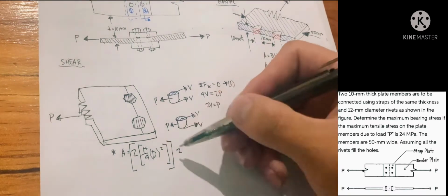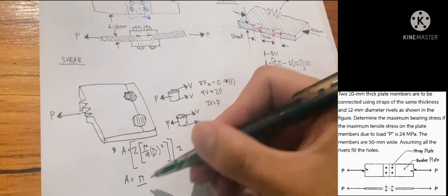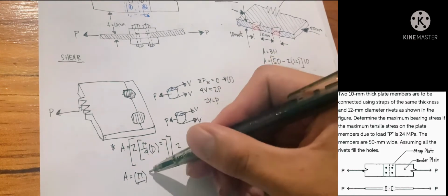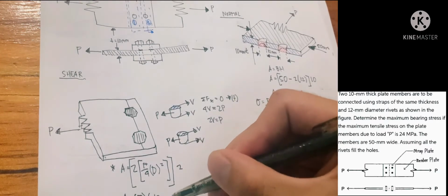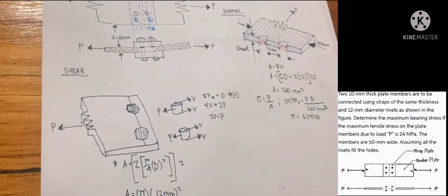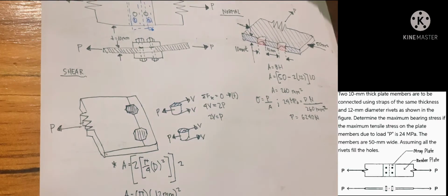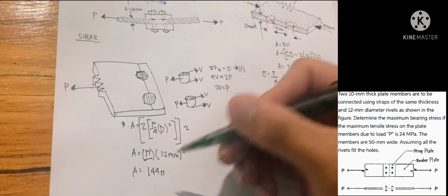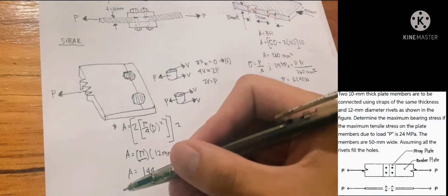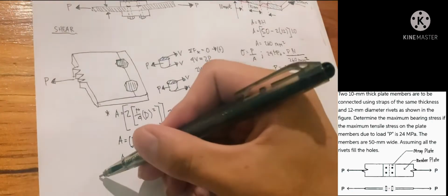So the first 2 is for our shearing formula to be in equilibrium, and the second one is because we want to consider every rivet, because from the illustration that we separated, we only considered a pair, but here if we want to look for our average, we will need to consider our other couple or other pair.